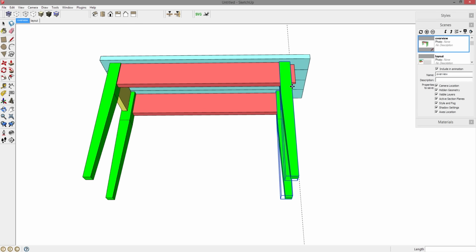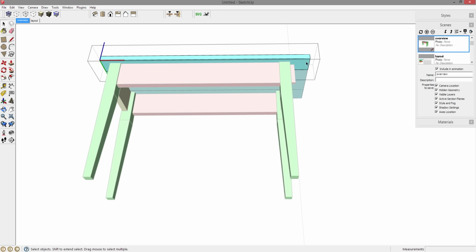So let's drop it off right there. And what I moved here, I need to subtract from the top. So let's double click to edit the top piece, use a window to select the face that I cannot see on that edge, P for push pull. Let's push this in that same 2.5 inches, enter. Spacebar, click to get out.